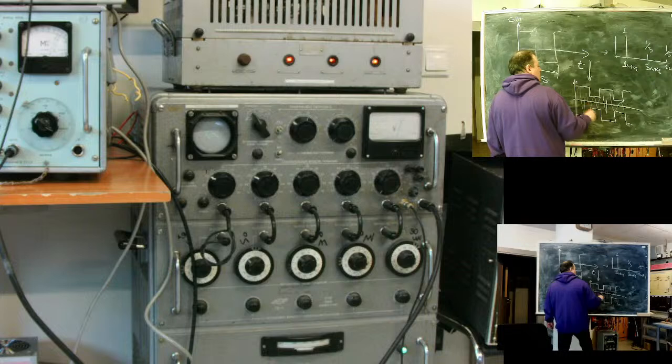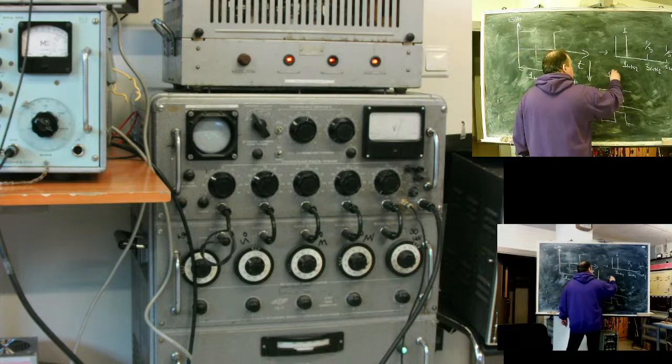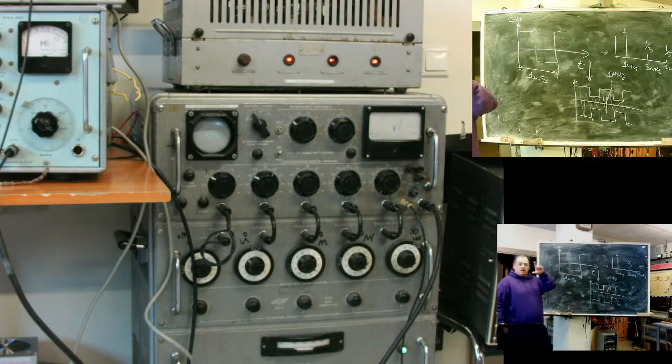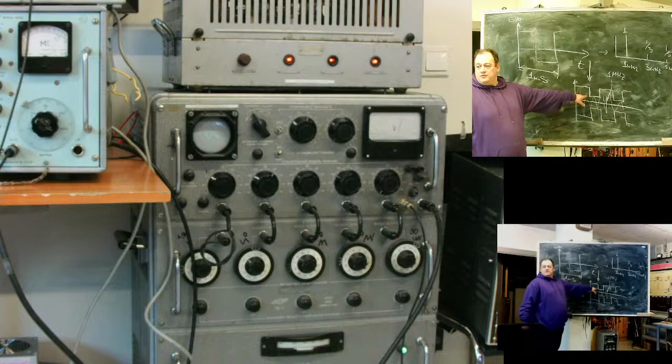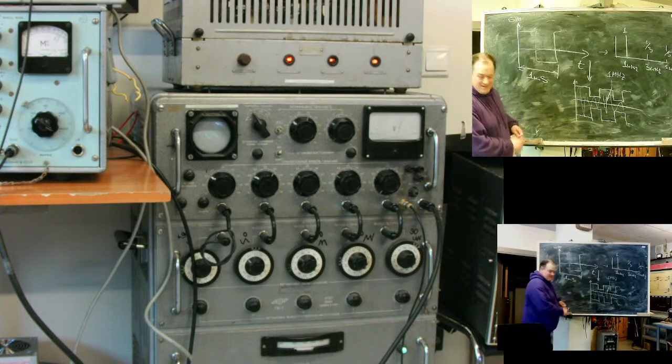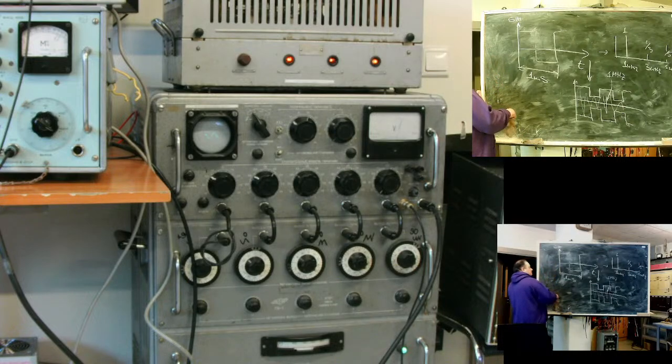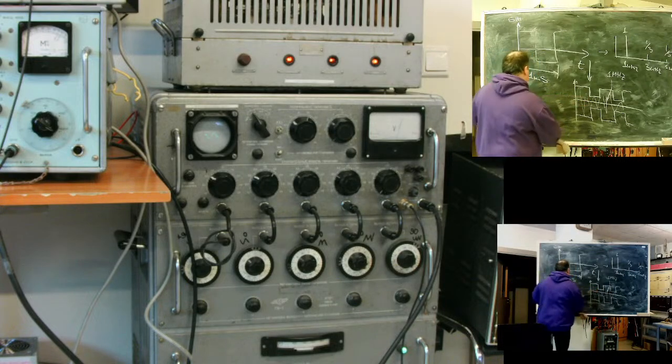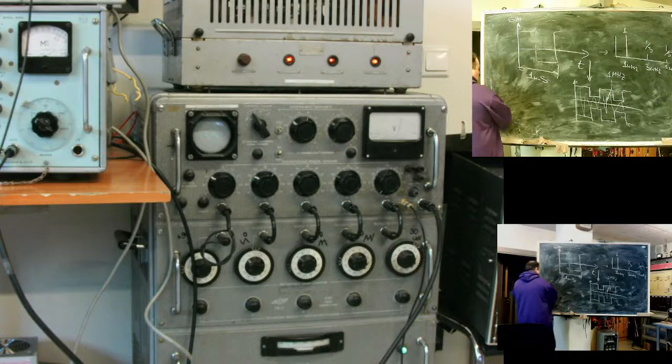The carrier is 1 megahertz. Amplitude modulation at 1 megahertz, approximately 300 meters, is the middle of the AM radio broadcasting range. What will be the spectrum of this signal? For this signal, the spectral diagram looks like this.